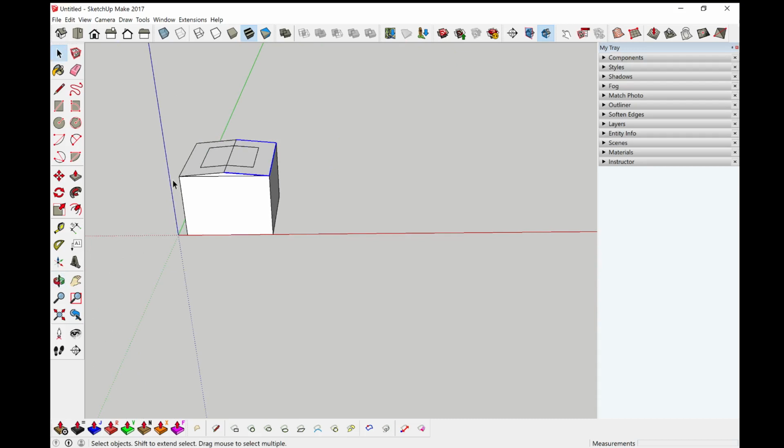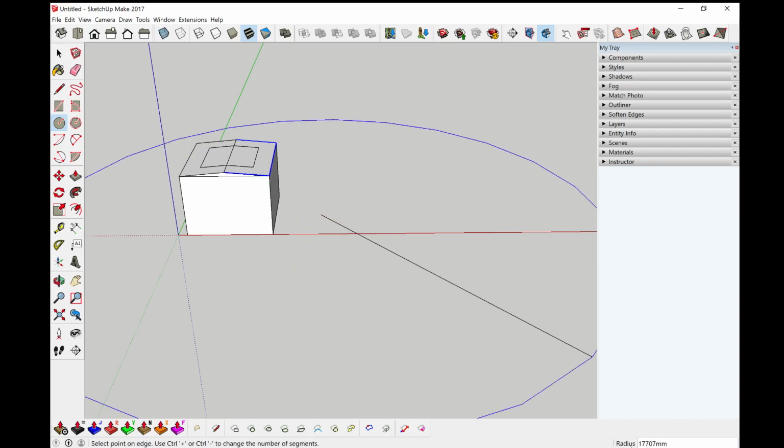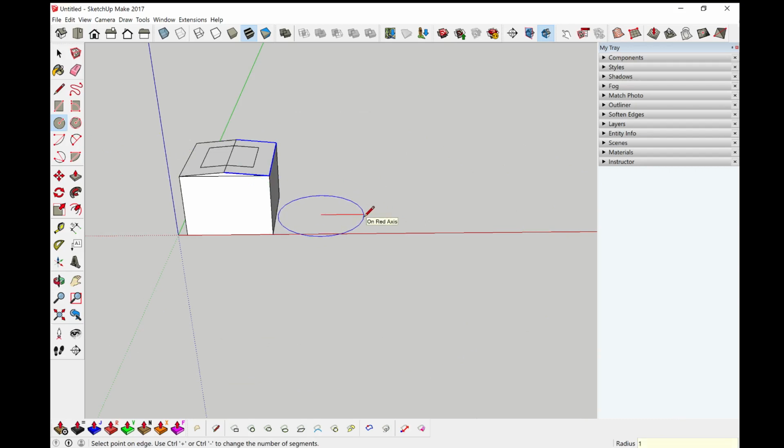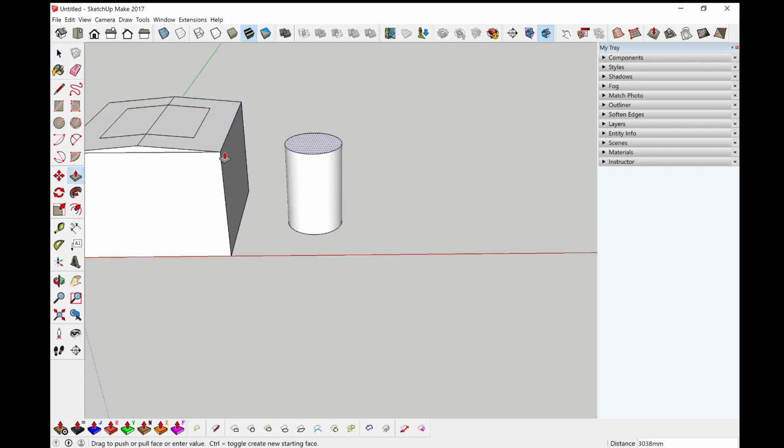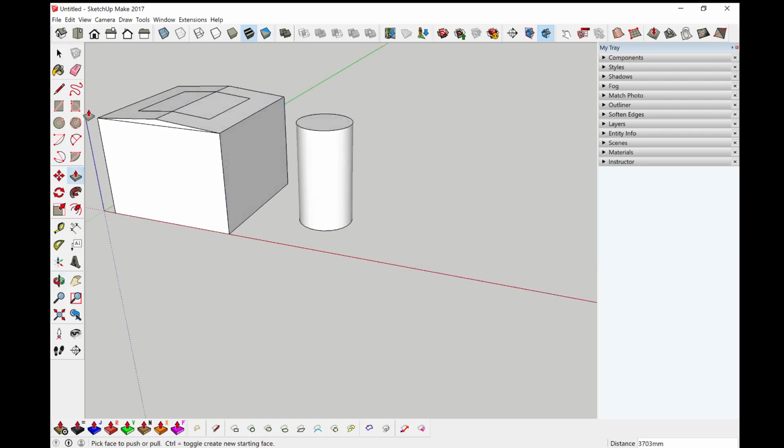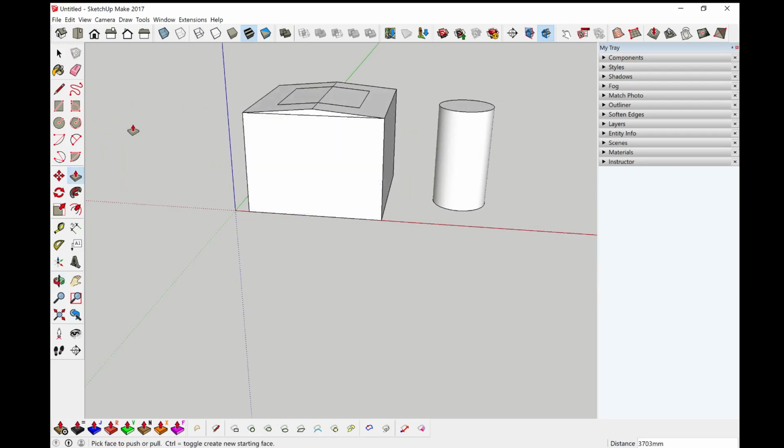Okay. And the next thing is to use the circle tool. Circle. The line that you see there is the radius. So let's just use 1 meter or 1000 mm. You press enter. That's about it. Then if you need to draw an arc, this is the tool. You press A. It will bring you to the default, which is 2-point arc. Left click once, left click a second time, and the third point, right, is something called a bulge.